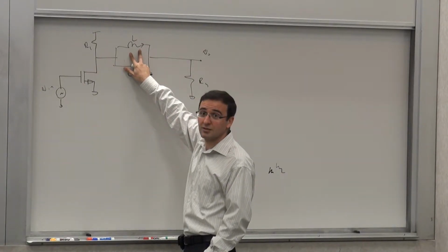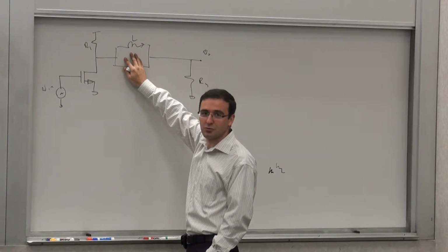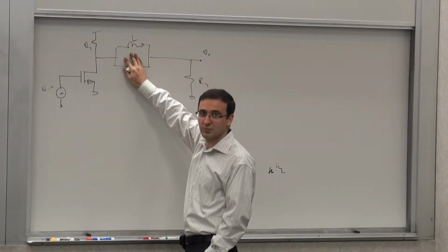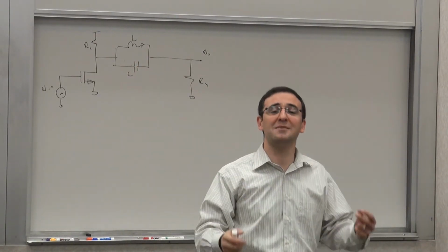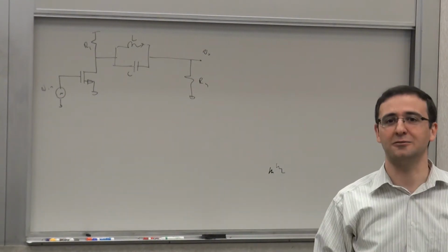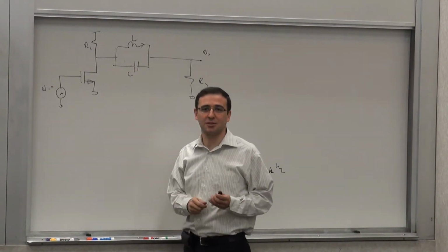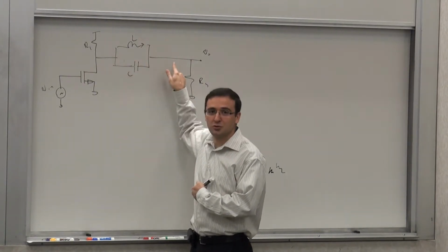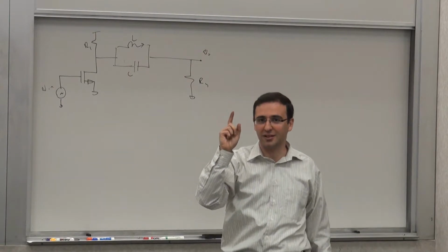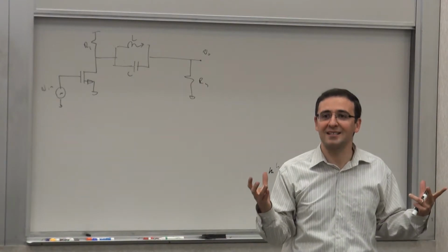If I open circuit it, I have to give it infinite value. Open this, and this is not there. Does anything go through? No. 1 zero? Are you sure? What was the criterion? Exactly. The criterion is the maximum number of elements that can be simultaneously infinite value. So now can I simultaneously make infinite value both of them and something goes through? Infinite value in this one means shorting it, infinite value in this one means opening it. So this goes through. This is one example that shows why that criterion was defined that way. They have to be simultaneously infinite value.